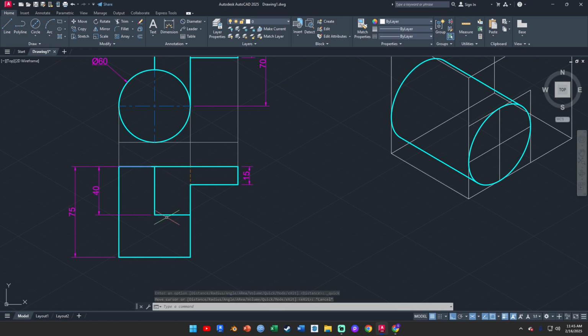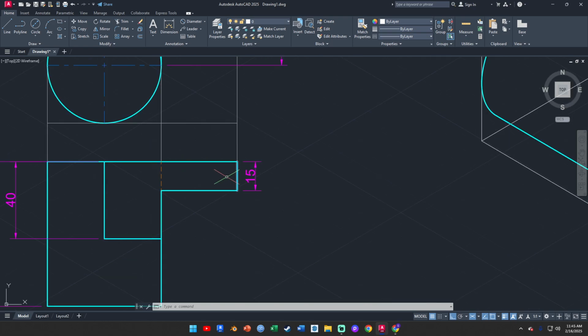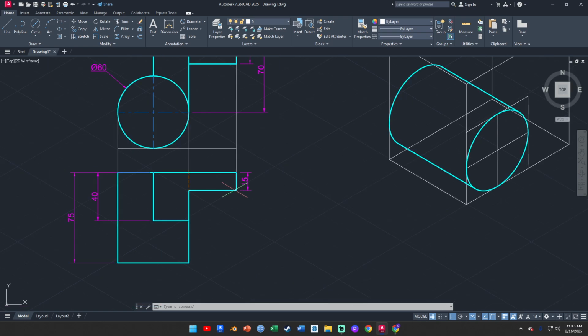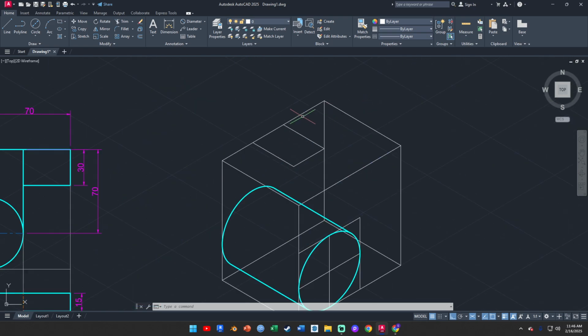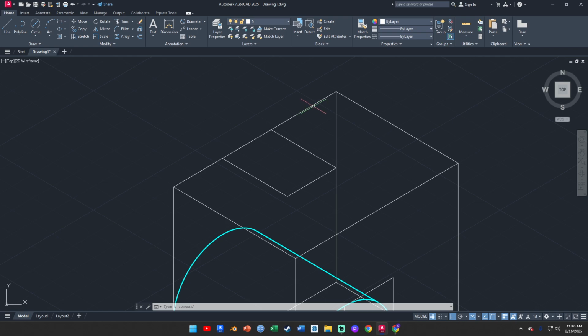And we have this rectangular part here. Now we just need this part here that looks like the handle, right? So we can see that the width here is 15 mm, right? So again, it's very simple. We just copy this line here, and you type in your 15, you move it down, you type in your 15, and we can just trim out the extra here, right?